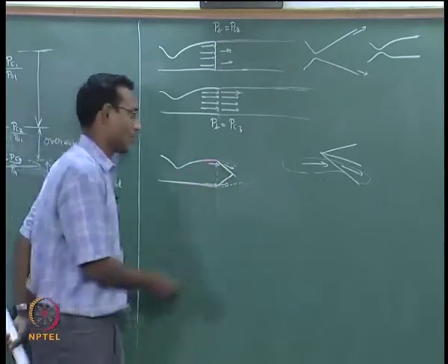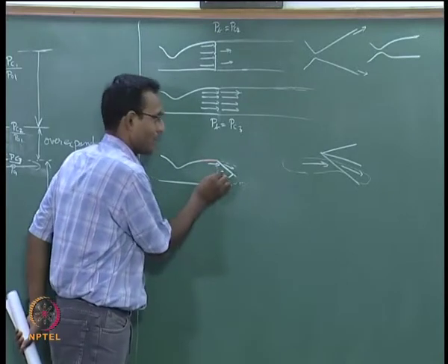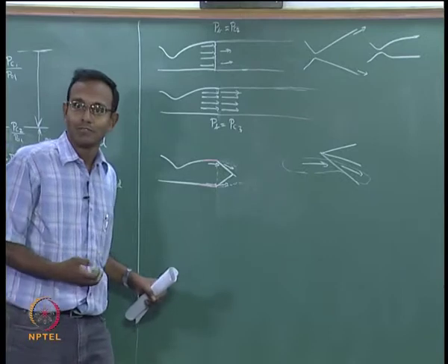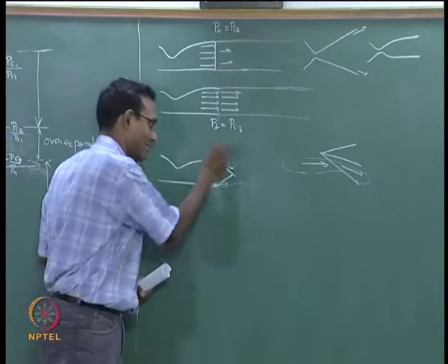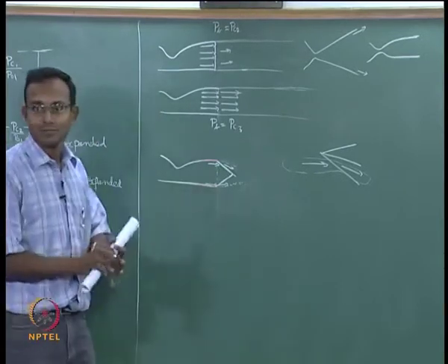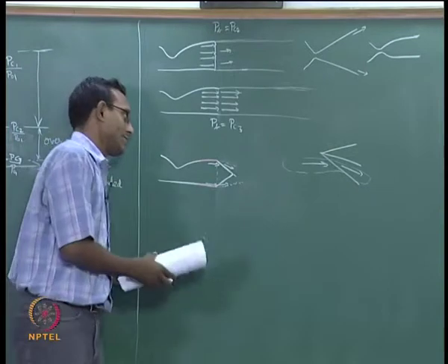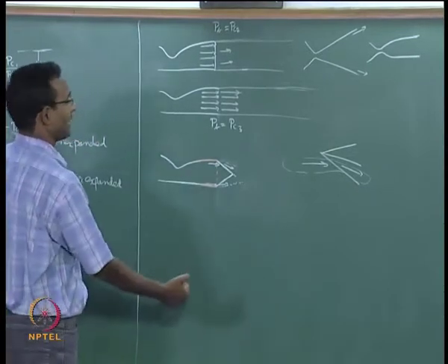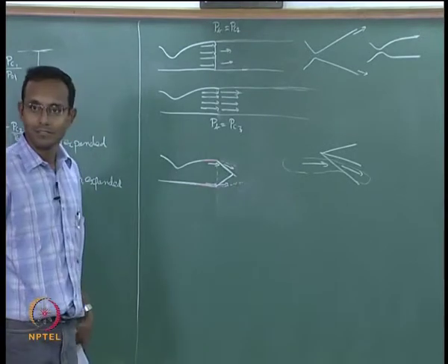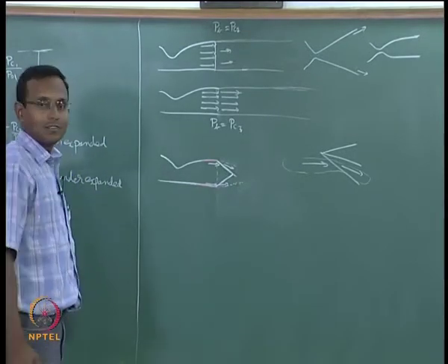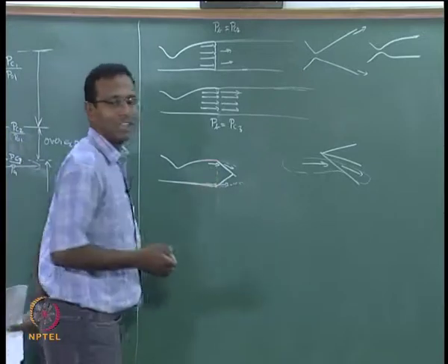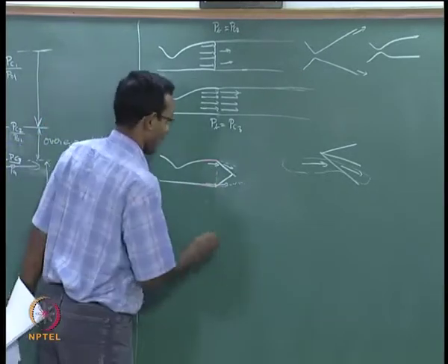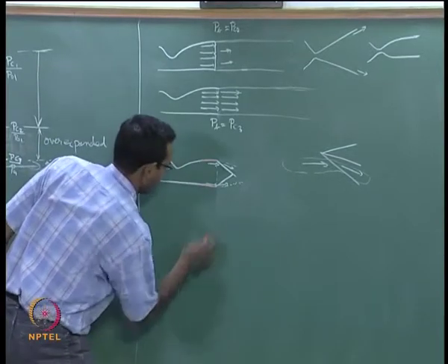So now I am going to talk about inside here one Mach number, above the shock there is another Mach number. That is the best I can do now. Okay, it is already 2 components at every section I think about. So the idea of this is this. Now I say I increase my back pressure a little more, what happens? The shocks have to be a little more strong.